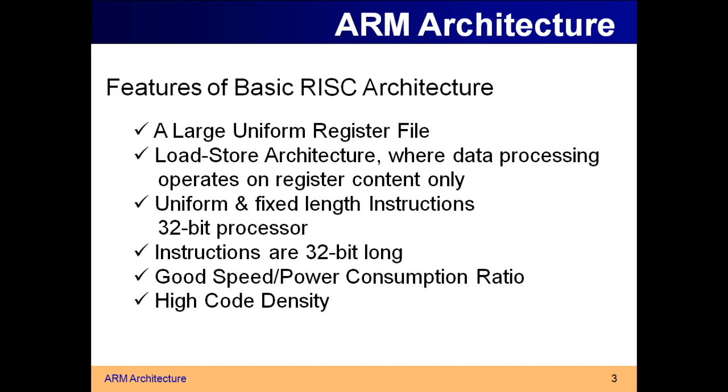Where the data operations are performed on the register content only. What do you mean by load store architecture? Say for example, I need to add 1 and 2. So 1 will be stored in a register, 2 will be stored in another register, and the operations will be done between the registers. Before taking the contents to the registers, where will the data be? The data will be there in the memory.